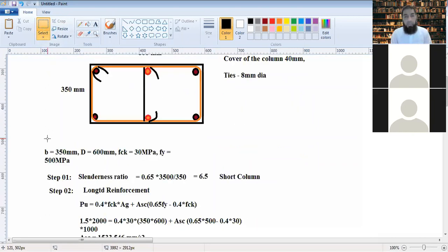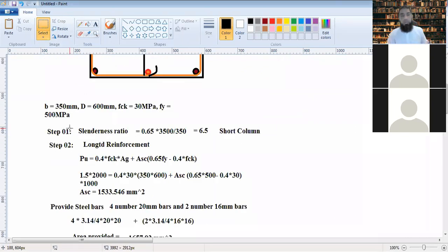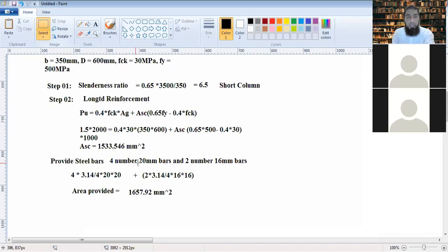Now this would have been a case when we were doing concentric loading, an axial short column. It is a short column. Whether it's axial, it's not completely axial. So the design has to be such that first of all we determine the eccentricity of this. The eccentricity that we determine by the code is different. That's the minimum eccentricity. Now we have to check the actual eccentricity of this column. So first of all we are going to determine the design strength of this column. To determine the design strength, we need to determine where the neutral axis is. The neutral axis is given in this question.